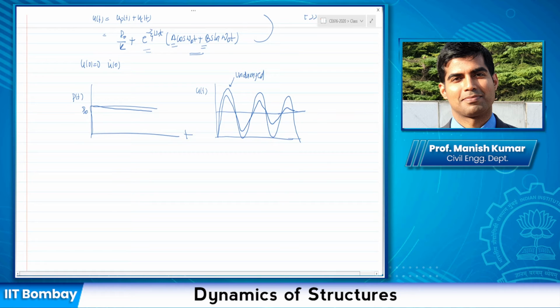That is for the cases where it is underdamped. In many situations, you make the system overdamped, so there is no oscillation at all. You increase damping so much, like damping greater than or equal to 1, so that it becomes an overdamped system and directly comes to rest. So in those cases, even if you apply a step force like this, there won't be any vibration. So what do we learn from this?